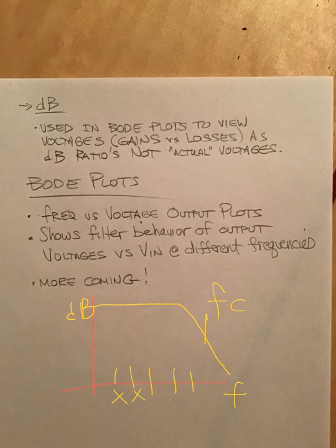For every frequency, there is a matching voltage, whether it's dying, whether it's living. And we compute this scale by plugging it into the dB formula, not the actual voltages. Now, could we use the voltages? Yeah, we could. But we're going to do Bode plots, frequency versus voltage outputs. We're going to show the filter behavior and what happens with V out and V in. More is coming, so stay tuned.